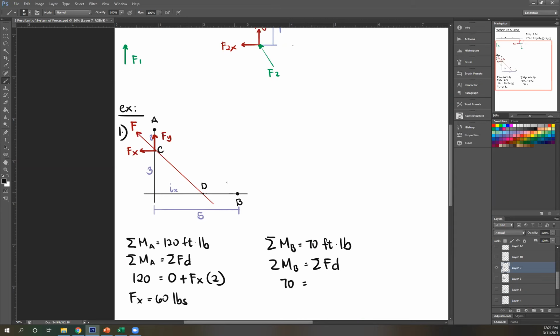So let's start with Fy. Fy now has a distance from point B, so that's not 0 anymore. So rotate it about B. As you can see, that's clockwise. So positive Fy multiplied by the perpendicular distance from B. If you extend the line of action of Fy, the perpendicular distance is just this, which is 5. So that's 5. Next, Fx. So rotate Fx about B.